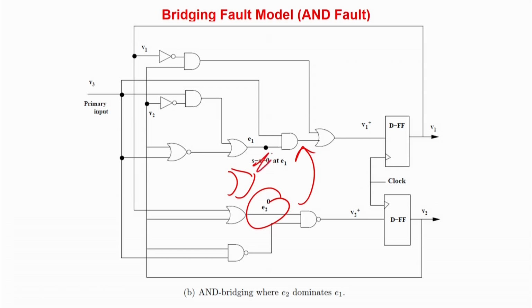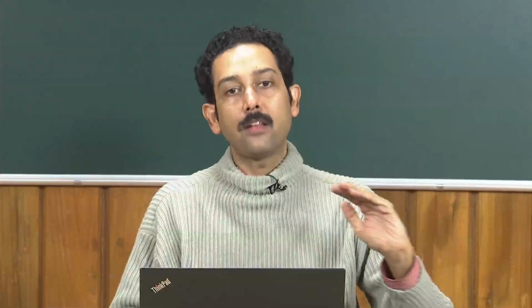So in this case you will be assuming the Stuck-at-1 fault over here, and here you have to explicitly have the value 1. So that is a dual you can easily calculate. Basically, what happens, and again I am repeating the key terms here, is that if you go for testing the bridging faults, automatically you will find that a lot of Stuck-at faults are already getting covered.